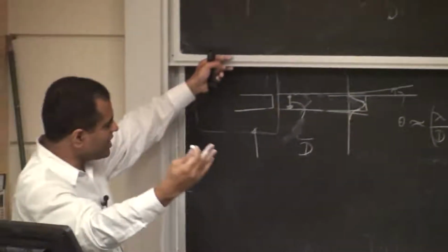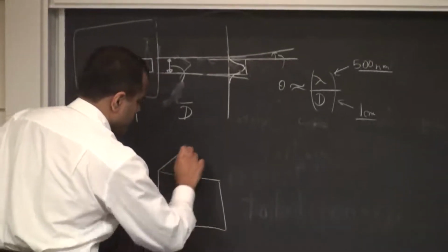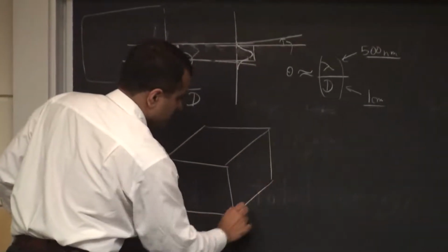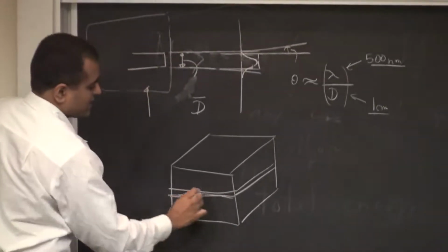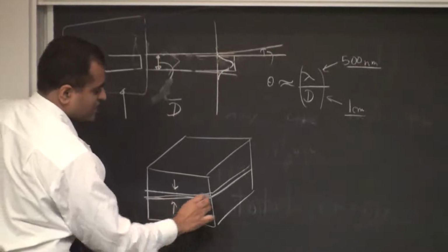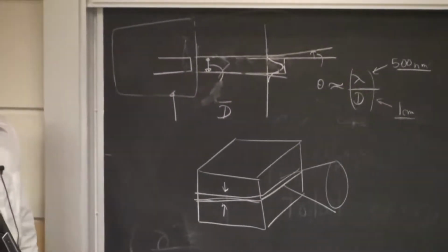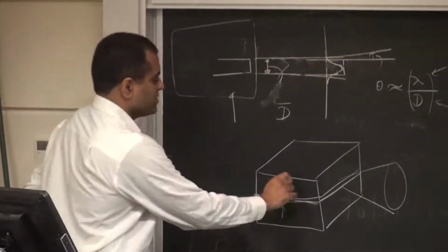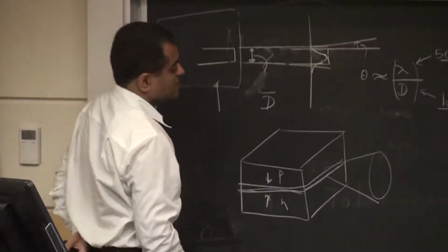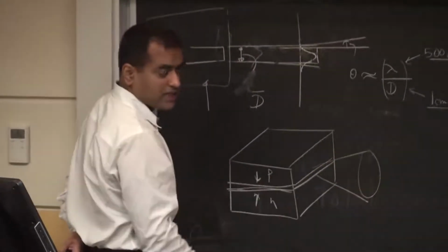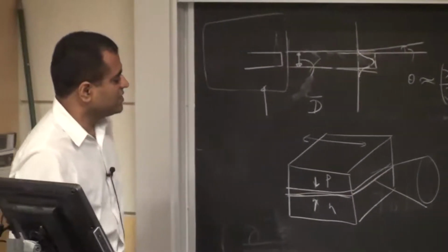The other family of lasers today, which is extremely important, is the semiconductor laser, where you take a piece of semiconductor PN junction or a PN diode, put in some quantum wells or quantum dots or whichever way you like, and then you inject electrons and holes, and out from the side comes the laser beam. This is a semiconductor laser. You get a PN junction, inject holes and electrons, create your 3-level system, population inversion, get light out. Here the waveguide is typically the semiconductor material itself.